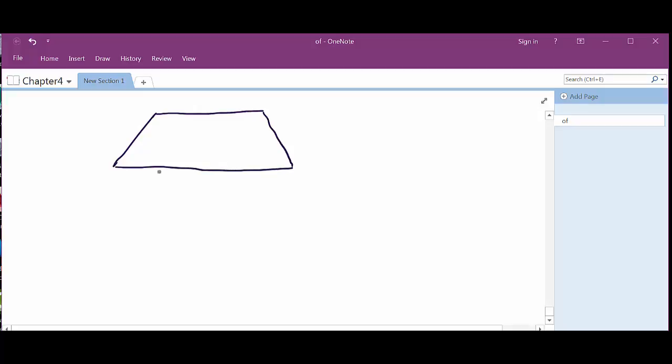Now A is a pin, so it's AY and AX. Everything's going vertical, so we'll say AX is going to the right. BY like this. BX is 0 because it's on a roller, right? So we've got 3 kips right here.